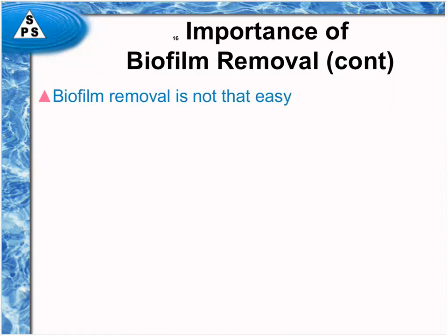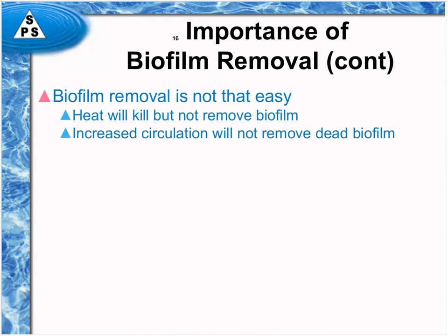Okay, biofilm removal is not easy. The heat obviously will kill the biofilm because it can penetrate by conduction down into crevices and cracks and all kinds of places and kill the biofilm that's there. But the heat does not have an ability to actually release the biofilm from the surface. It just kills it where it lays.